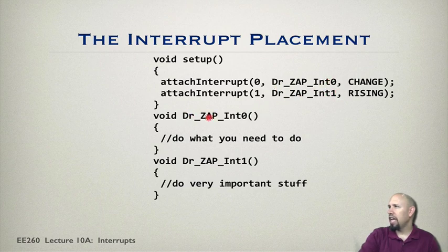So what this name is, this is the name for the interrupt service routine that will be called when an interrupt occurs. Okay, interrupt service routine has to be of type void, and actually it can't receive an argument. But inside you can do stuff.